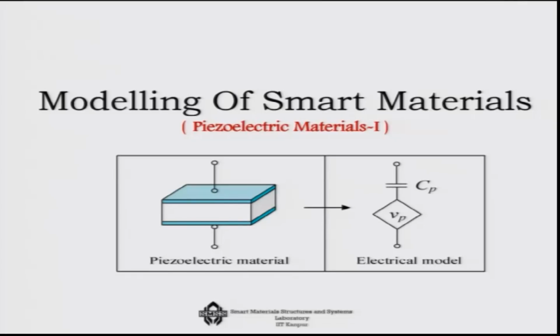When we talk about modeling of such smart materials, starting with the piezoelectric materials, we have to keep in mind that a piezoelectric material has an electrical model, in which you can consider it to be a voltage source along with a capacitance attached to it, and also a mechanical model, which is some kind of a spring system. So, you have a mechanical model and an electrical model of the system.